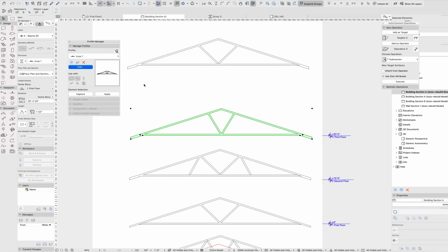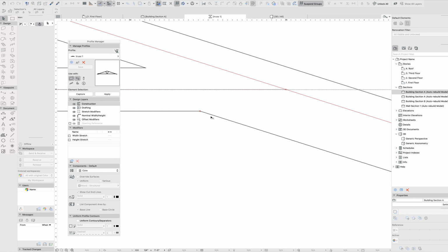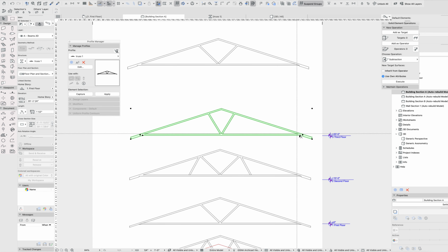Additionally, if I look at what I've done with this beam, I've added a few hotspots in here, and you can see what that does right away. So the hotspot right here, for example, in section adds a hotspot right here so it can sit right on the plate. Because I'm drafting it out with fills, there is no centerline edge line. It is what the fill represents as the extrusion.